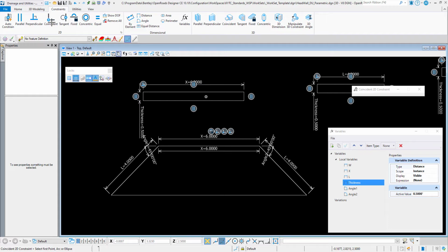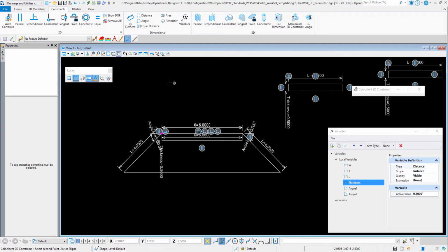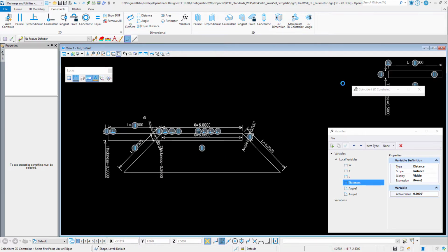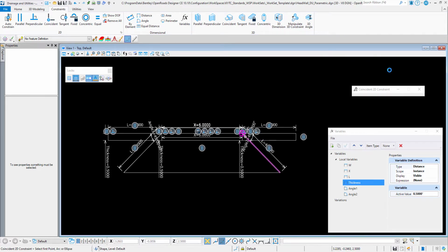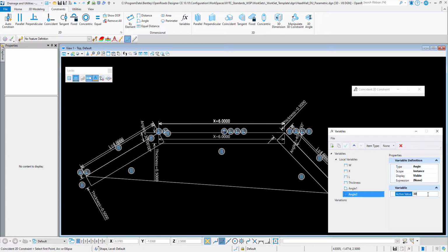The next step I'm going to do is affix the center point by selecting that static first point to the new rectangles that I drew, where I want them to be anchored to. So the first step is I chose a center for the back X because I wanted to expand that way, but I do want my coincident constraints on the wings to be at the edges. And so I'm doing it for both sides. And I'm making sure that those wings are on the inside of this shape.